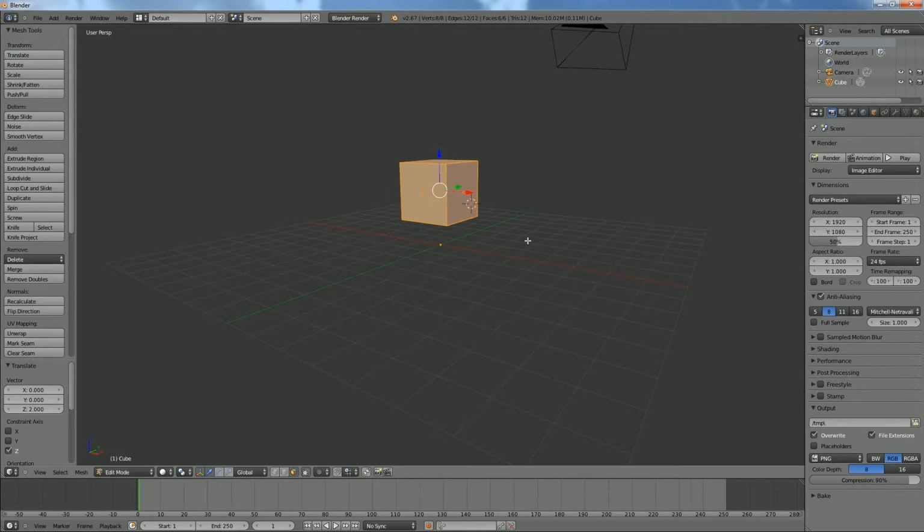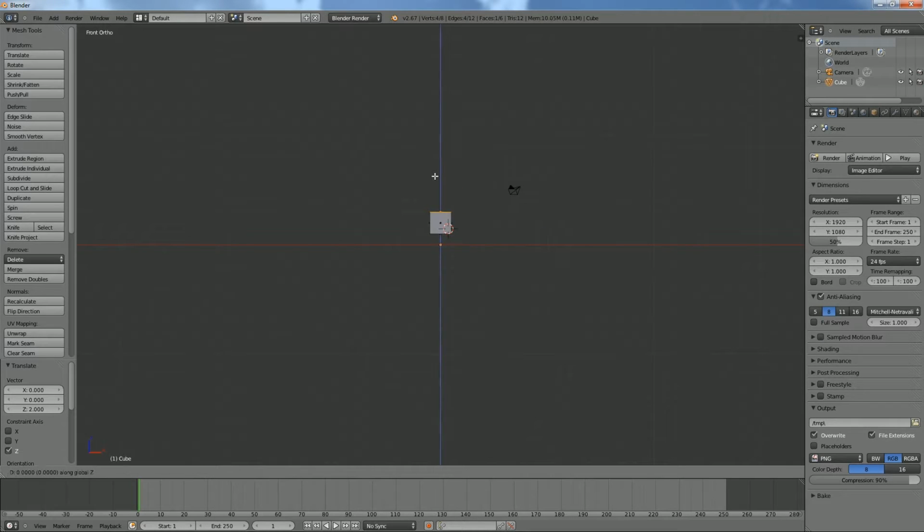And then we're gonna go into orthographic by pressing 5. And we're just gonna work at the top of the building a bit right now. Or I guess the middle, not the top. So we're gonna select the top face, and we're gonna make it a little bit bigger. So we'll go G, Z, and we'll make it about 8 units or so bigger. And then we'll move it out on the side.